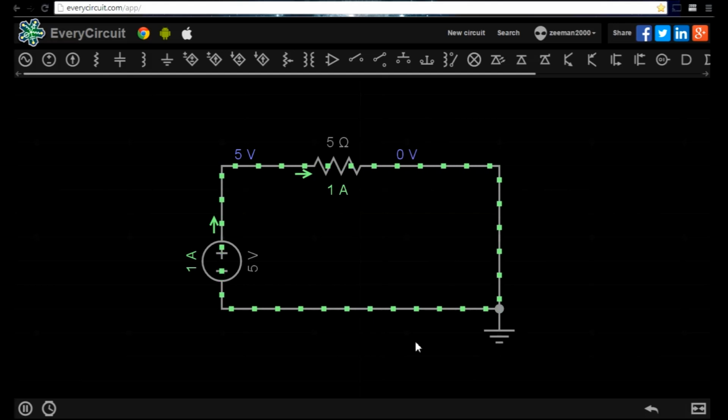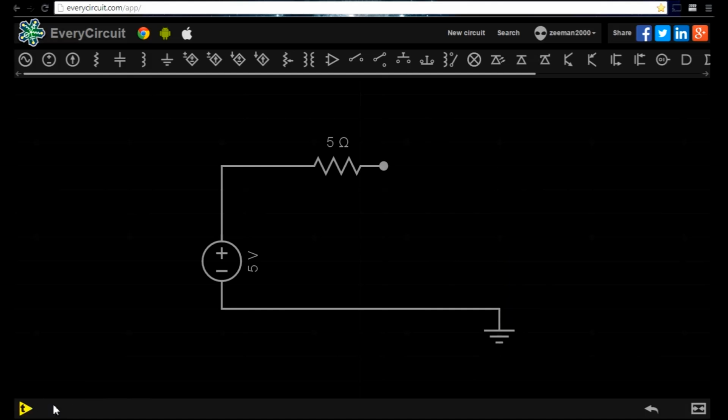a circuit. We'll firstly add an LED to the test circuit we built in the last tutorial. First we need to pause the simulation, then hit the rewind icon. We then double click the connection after the resistor and click the cut icon. This removes the connection.